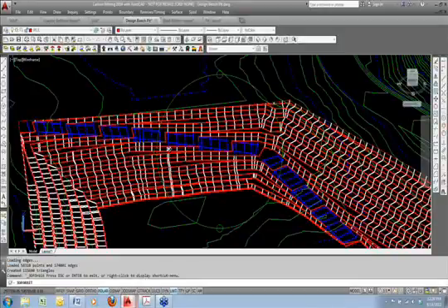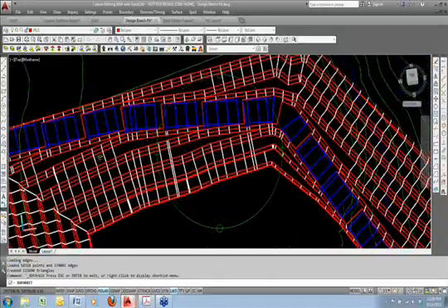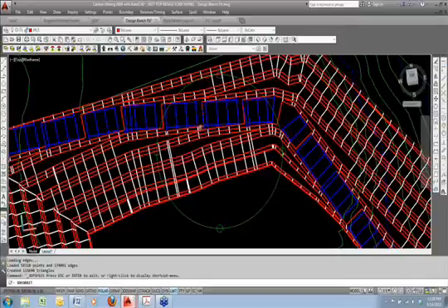It's a little easier to see when you're in plan view looking straight down. You can see how this bench has 50-foot width here, and then it begins to taper down to 0. You want to make sure these slopes all stay the same. You don't want to have your changing slope on your high wall, so it's very, very unique how it does it now.